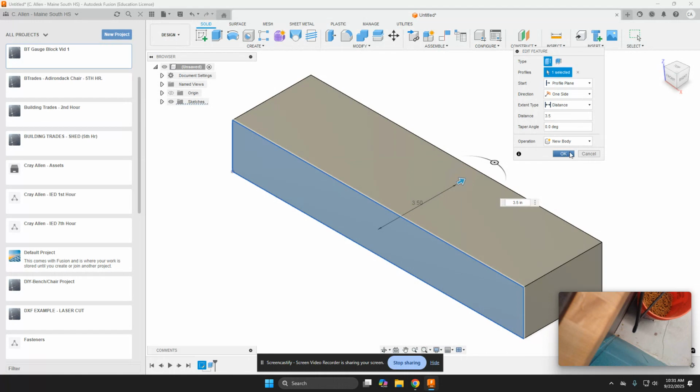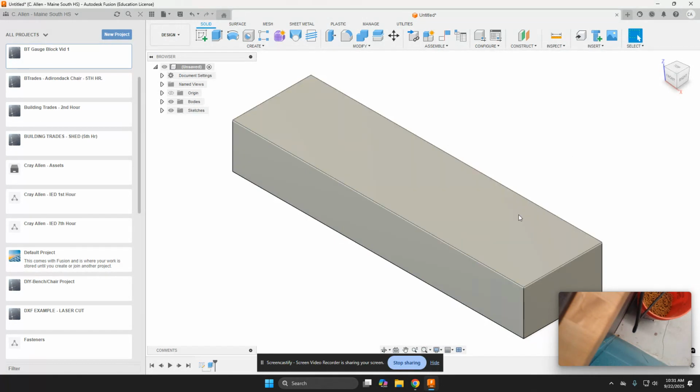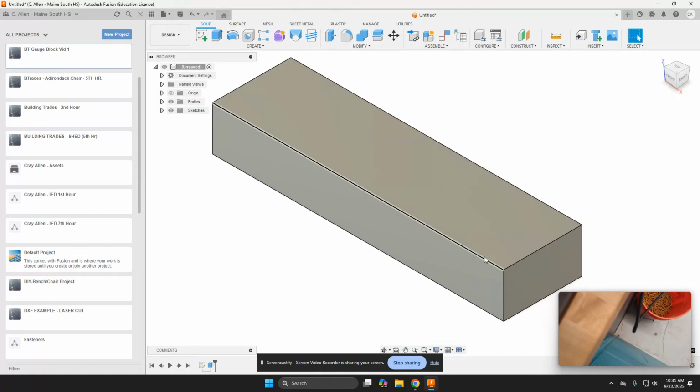Okay, all right, so it's going to be an actual size, right? So once you change that direction, just hit OK, and boom. Now we've got that. Now the same thing applies to the height of your wood members in an interior stud wall as it does to the depth. We changed the depth from 4 nominal to 3.5 actual. What are we going to do with the height?